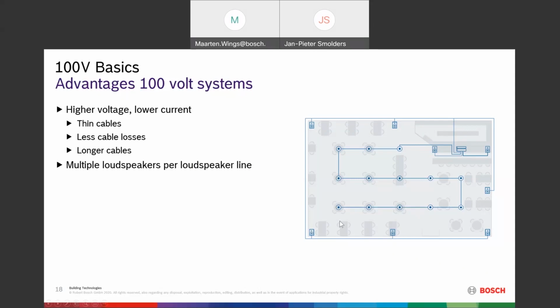And you can even add loudspeakers later on to the same loudspeaker line. You don't have to make any calculations. The only thing that you will have to know is the amount of power that is connected to this amplifier, so the total loudspeaker load, so that you don't exceed the maximum power that this amplifier can deliver.